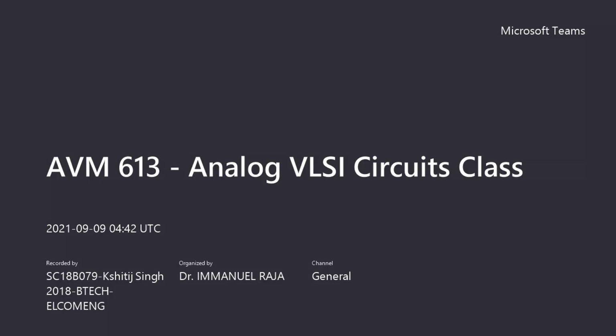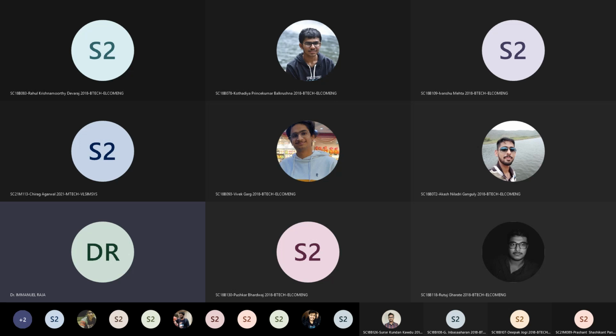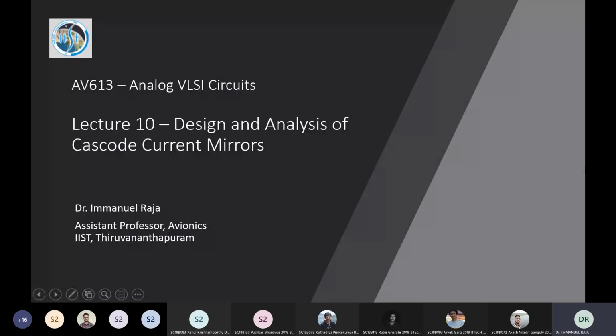In yesterday's class, we were looking at Cascode current mirrors, and we saw that it has two major advantages. If you recall, it solves two problems. One is the problem of systematic mismatch, and the other is the problem of output impedance, right? Yesterday we saw how this Cascode structure solves the problem of systematic mismatch.